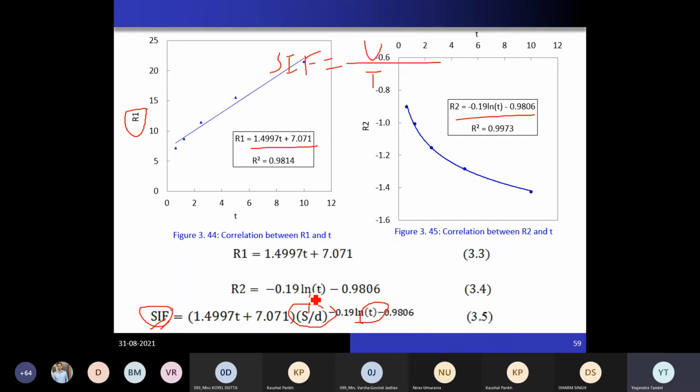You might have a value of spacing. That means based on your stone column basic theory, based on IS 15284, you can choose the value of spacing S, and you can come up with a diameter of the column. T requires the value of J and the value of E. Based on the properties of soil and properties of geosynthetic, you can calculate the value of T. So T is nothing but J upon D into E. E means the modulus of the surrounding soil, J means the stiffness of geosynthetic, and D means diameter.